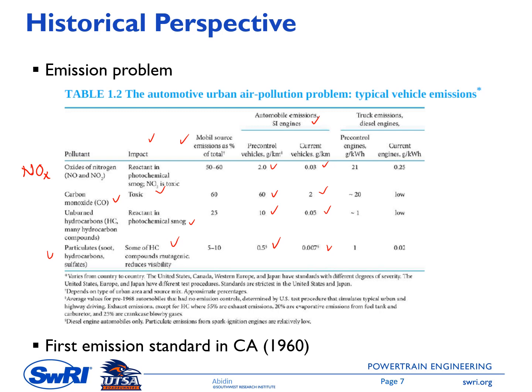After applying an after treatment system, NOx, for example, is about 0.03 gram per kilometer from this SI engine. It is higher for a diesel engine, a compression ignition engine, at 0.25 gram per kilowatt hour, but that is a different unit. But I believe NOx from a diesel engine is higher than the one from a spark ignited engine.